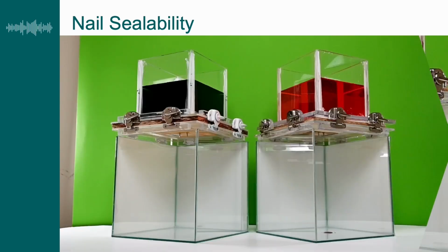So 2 nails were driven into each underlayment and through the deck, and they were underdriven on purpose to simulate something that's commonly seen in the field. Light foot traffic was applied to that area to simulate the movement around the nail heads, and a 12 by 12 sample of the roof deck and underlayment were taken out from that deck and placed in these acrylic tanks with 2 chambers, a top chamber and bottom chamber, and water with food dye was placed in each chamber and was observed, right? On the left-hand side with the green water, you have a polymer-modified self-adhered underlayment. On the right-hand side, you have a synthetic underlayment with that red-colored water.